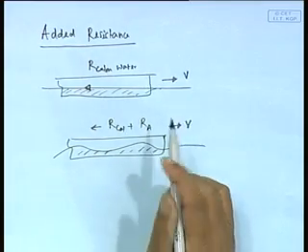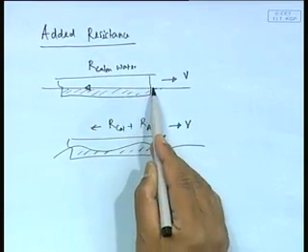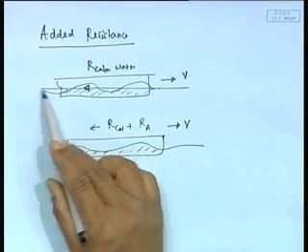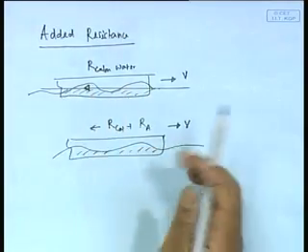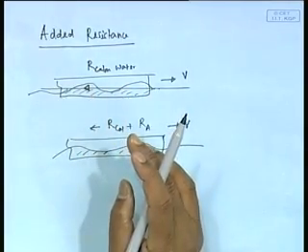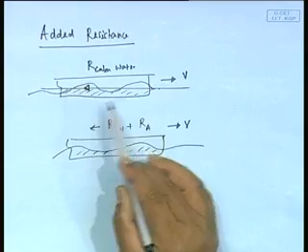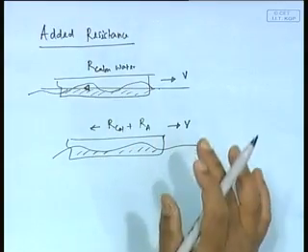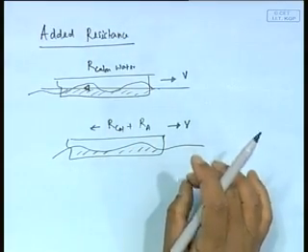Why I tell you that, remember, even when I go on calm water, I actually have a wave formation. Even when I go on calm water, I have got a wave formation around that, isn't it? Yet, if you recall correctly, we do not consider that for our wetted surface calculation. The reason is that this wave is up and down, and the net wetted area we think does not change significantly.